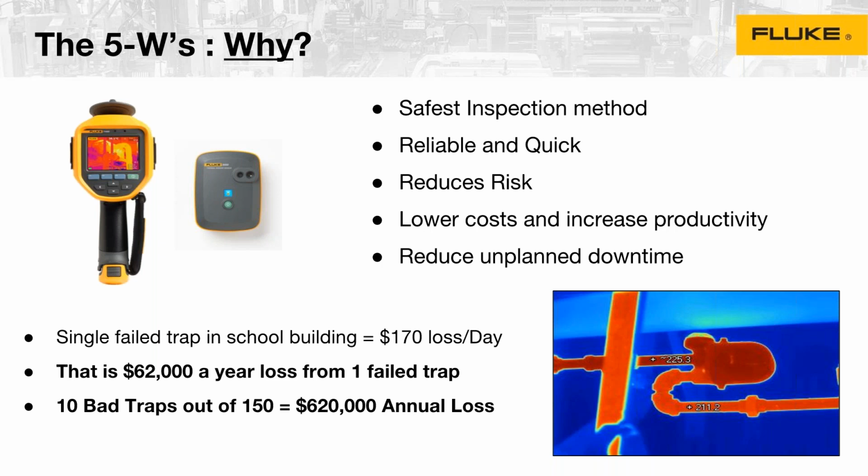And they said, no, we have not. They started using it, and come to find out that one of the motors, which was showing decent vibration measurements, was showing a much worse picture in terms of the infrared. It turned out it was not a vibration issue on that motor, it was electrical. So having the ability to combine multiple parameters, as an example vibration and thermal imager, really shows the entire picture of what you can find.